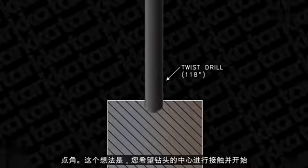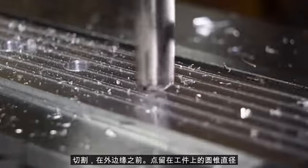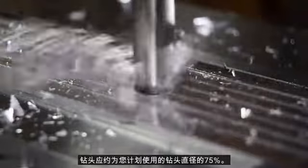Typically, the spot drill angle is chosen to be equal to or greater than the drill point angle. The idea is that you want the center of the drill to make contact and begin cutting before the outside edges. The diameter of the cone left on the workpiece by the spot drill should be about 75% of the diameter of the drill you plan to use.